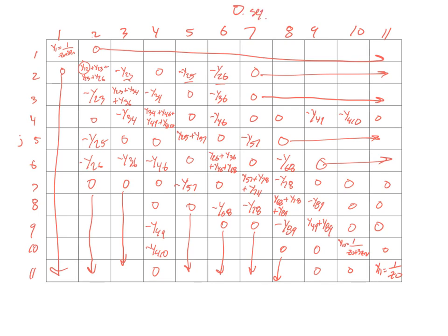And now you have enough information to go ahead and continue on. So we are on, at this point, to step 5. We just built our Y buses. Now the next thing we need to do, in both cases, for step 6, is to invert our Y buses to get our Z buses for all 3 diagrams.